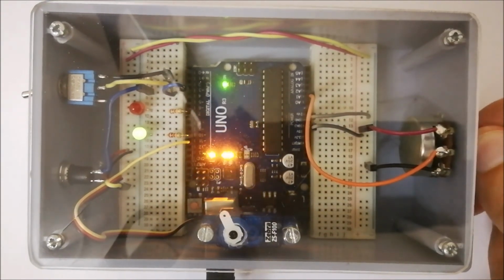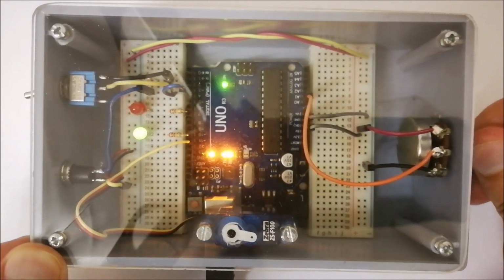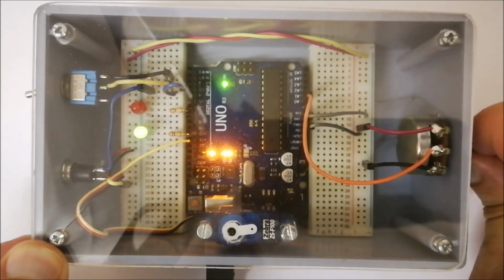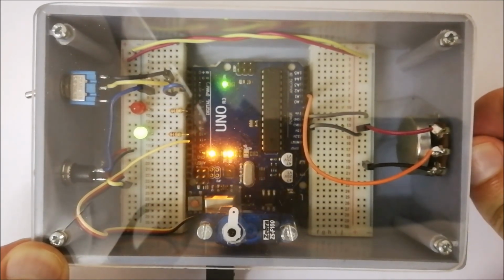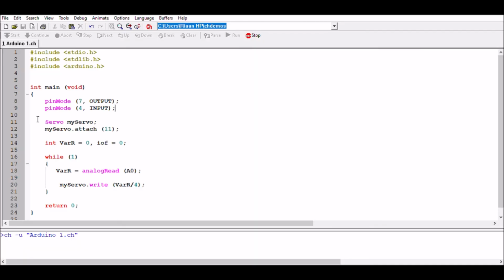So these are things to keep in mind for future projects, and you can use very similar code and techniques to control motors and therefore the wheels on a specific robot. What we did over here is we had Servo myservo. Please note that there's no dot in between over there, otherwise it might not work.